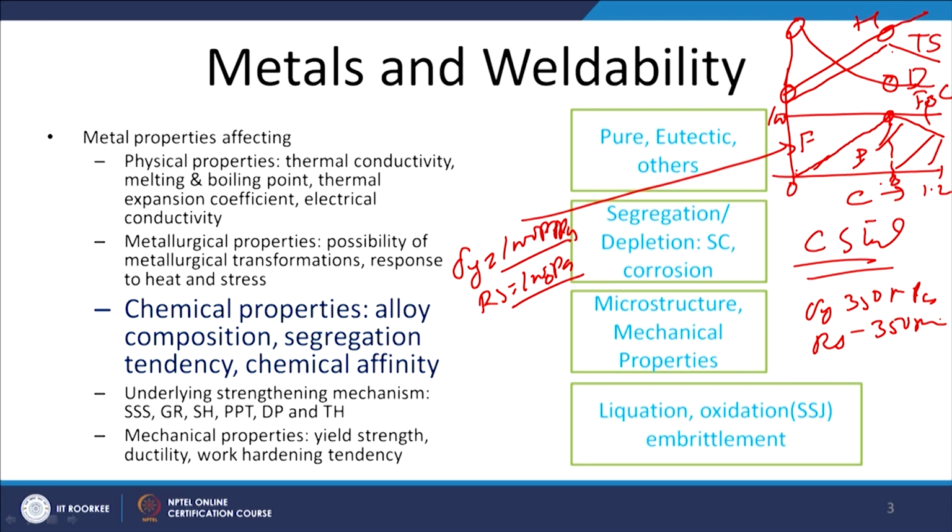because higher levels of stress will lead to deformation and yielding of the material, and the residual stress will be eased out, that is why the maximum magnitude of the residual stress which can be retained in the weld joint will be equal to the yield strength of the metal. So, the higher the yield strength of the metal, the greater will be the residual stress.